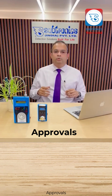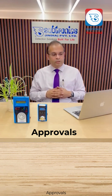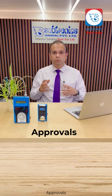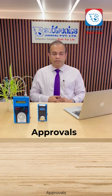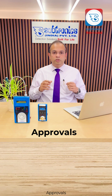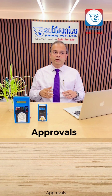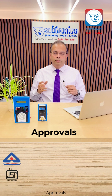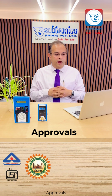Then let us look at the norms and approvals in the market. The detectors at the site of operation can be zone 1, zone 2 or zone 3, depending on the type of application in which they are installed. These detectors should carry approval, especially for combustible gas. Our detectors carry the ISI mark from the BIS office. We also have approvals from CMRI and PESO.